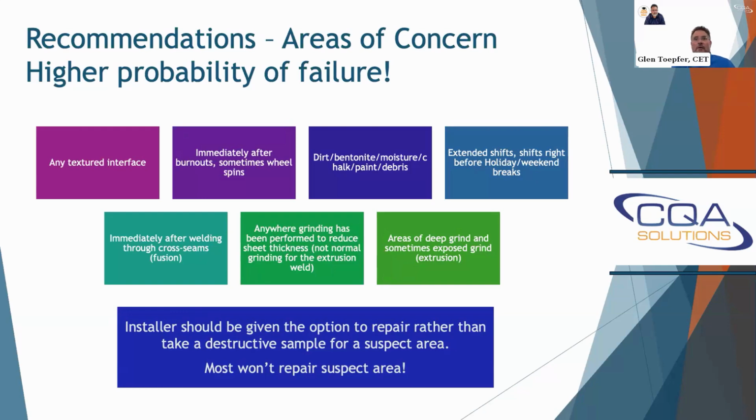But again, you've got to weigh that too. The installer starts putting 10 repairs on a seam saying, hey, I'm being proactive here. You might want to sample the seam and figure out what's going on there just to verify it. But there's got to be a balance there. But repair rather than cut a hole is better, in my opinion, in most circumstances.